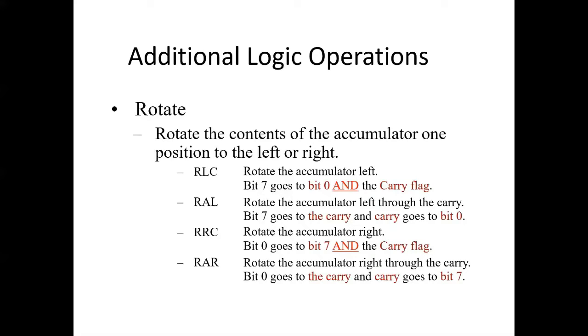RAR stands for rotate accumulator right involving carry flag in rotation. It rotates the accumulator contents to the right by 1 bit position. As can be seen, after a rotate right operation, the bit moves out from the LS bit position and goes to the carry flag, and in the process moves out the earlier carry bit to the vacancy created in the MS bit position. We have to note that the carry flag is involved in the rotation, and it is a 9-bit rotation of accumulator and the carry flag, and only carry flag is affected in the execution of this instruction.